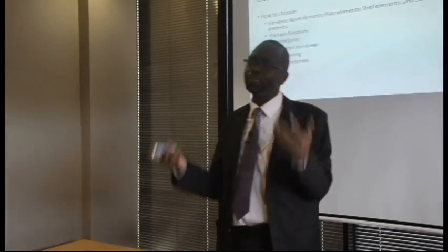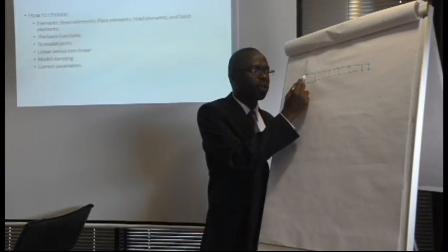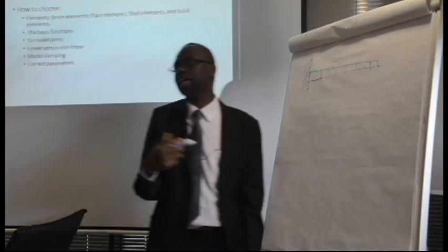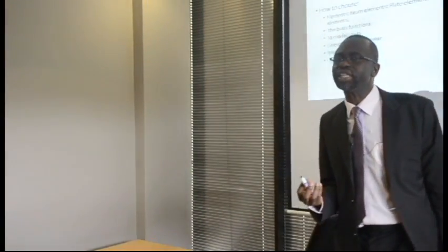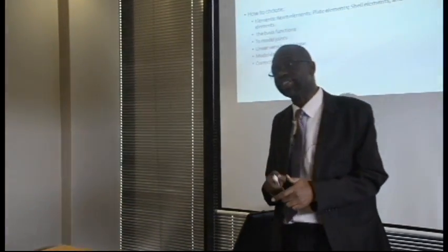How do you model damping? One of the biggest problems that we have been dealing with in this area is, how do you model damping? Normally, if it is aluminium, then the damping is assumed to be proportional, because it is lightly damped, and you can more or less use proportional modeling, but that is another area that you have to deal with. How do you know what the material properties of these elements are? If it is aluminium, what grade of aluminium? If it is steel, what grade of steel? That information that you can just go and pick up from a chart might not necessarily be correct.